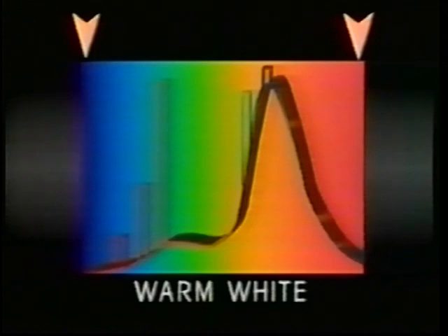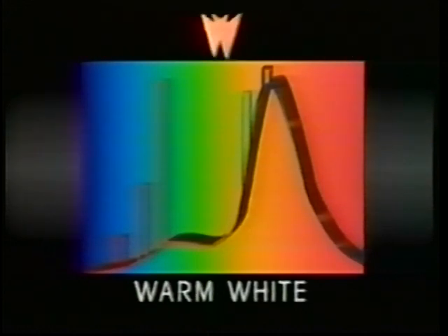When applied to fluorescence, the spectral distribution reveals the different nature of its light. In other words, not all wavelengths of light are strongly represented by the phosphors in a normal fluorescent lamp. In fact, some visible frequencies are absent, while others are very strong. This is the SPD of a warm white fluorescent lamp, showing high relative energy in yellow and orange, and very low energy in blue and red, and even a dip in the green between blue and yellow.